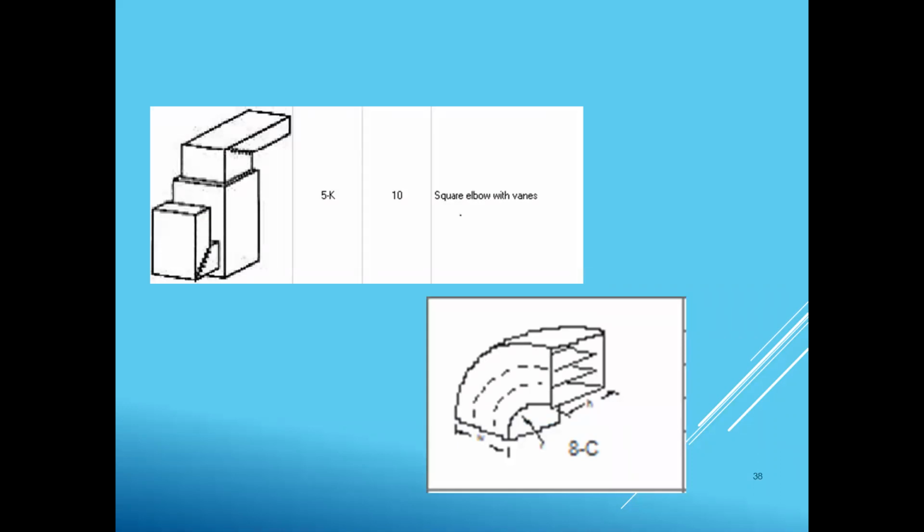Now, I always say, hey, please provide the pictures of the fittings used in design. And hopefully that seems kind of obvious now, because we saw one fitting that went from 20 feet to 120 feet on a fitting that they typically use, which would mean, guess what? If they use those fittings in the field, this system won't work. It won't work as designed, that's for certain.